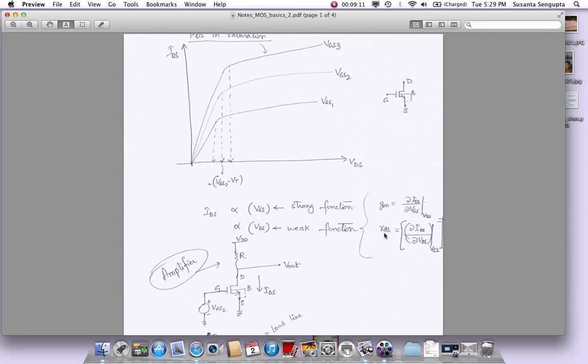So it's important to understand that whenever somebody says small signal model, that means if we look at VGS or VDS in this case, something is causing a perturbation which is small compared to the DC values that are already there. Okay, so we talked about VGS. Similarly, we can talk about VDS. Let's say this gate to source is a constant DC value, and no perturbation happened here. Nothing changed this value at all, not by a microvolt, not by a nanovolt.